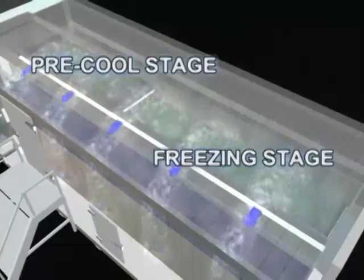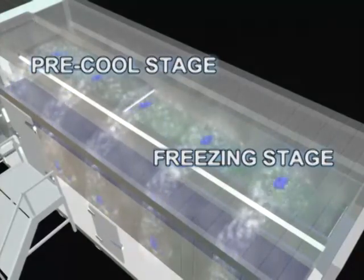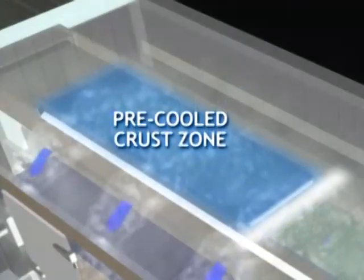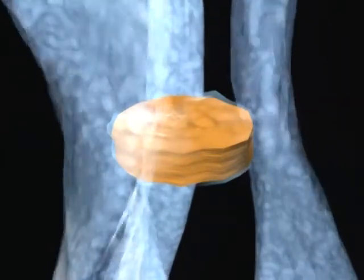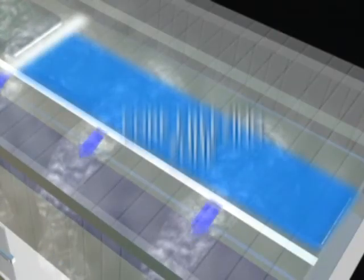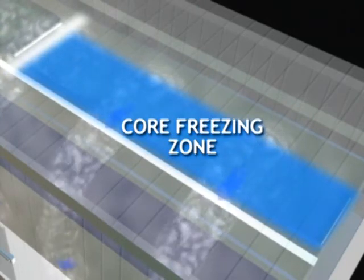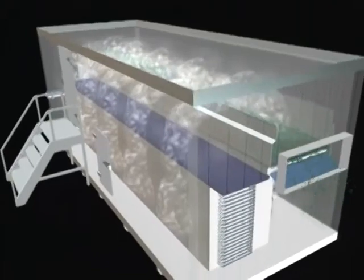Once in the freezer, it is divided into 2 zones, the pre-cooled crust zone and the core freezing zone. In the pre-cooled crust zone, the product is agitated and crust frozen to seal in the moisture and assure product separation. The product is then transferred to the second zone. In the second zone, the core freezing zone, the crust frozen product is continuously agitated by the fluidization effect, where the product core and remaining latent heat is removed to complete its freezing cycle.